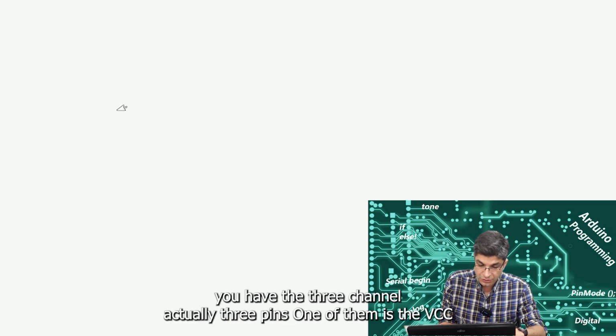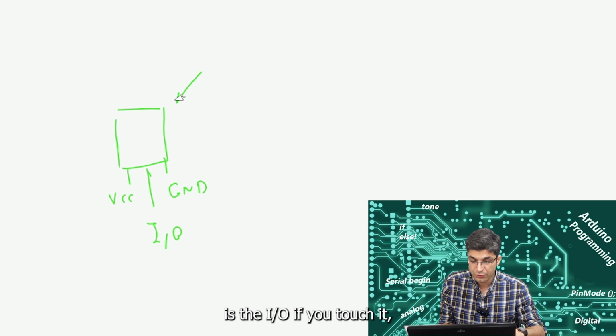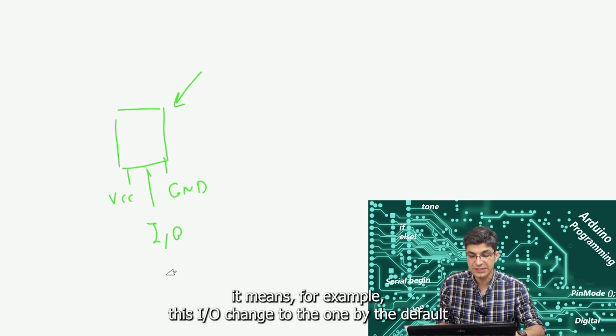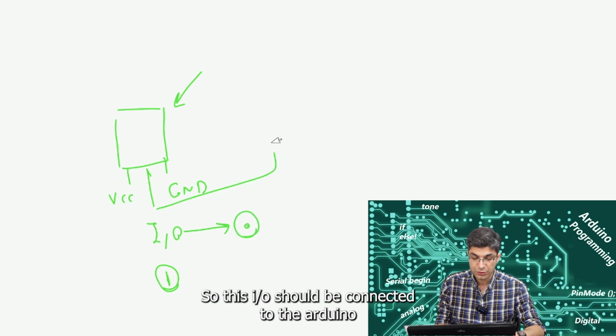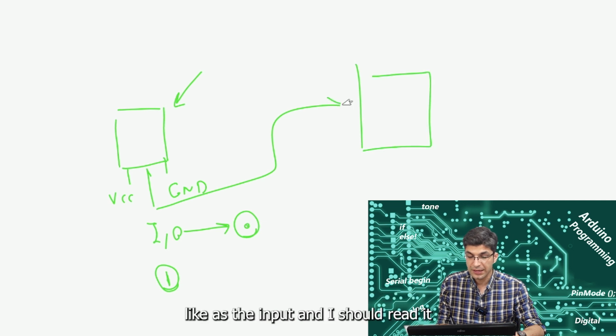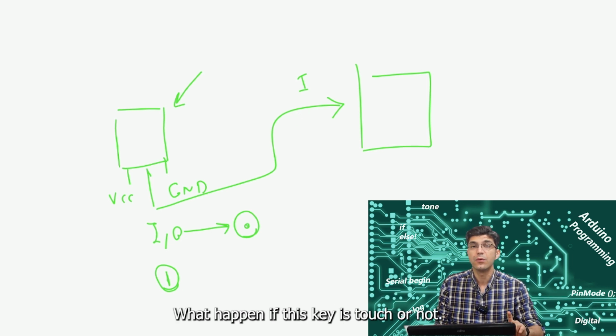But if you don't know it, it has three pins. One of them is the VCC, one of them is the ground, and the other pin is the I/O. If you touch it, this I/O changes to 1 by default, and if you don't touch it, the I/O pin is 0. So this I/O should be connected to the Arduino as an input, and I should read it, and we get results based on our decision of what happens if this key is touched or not.